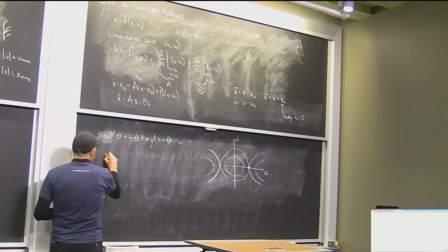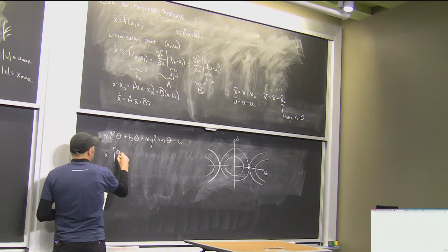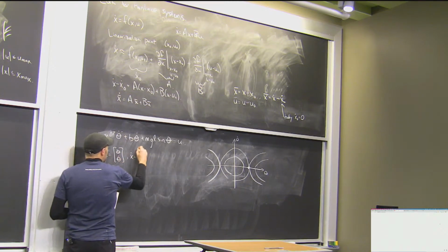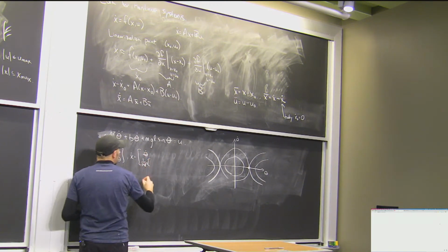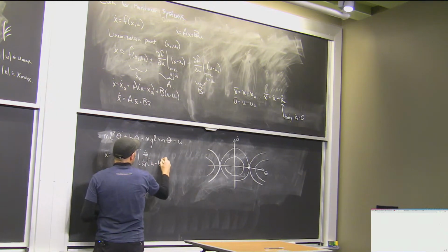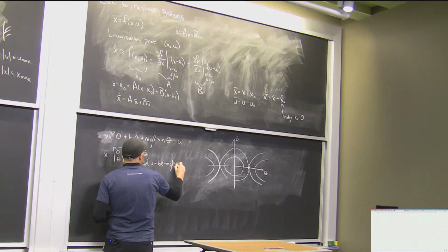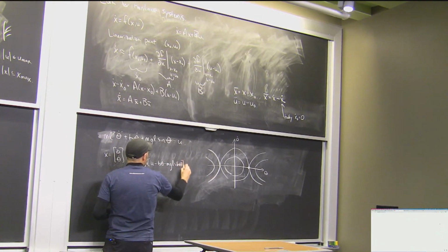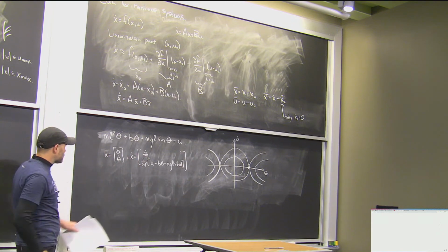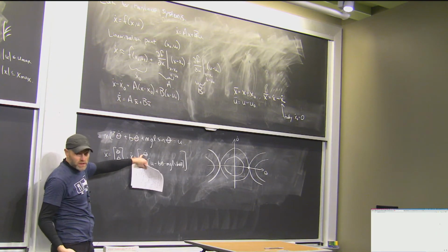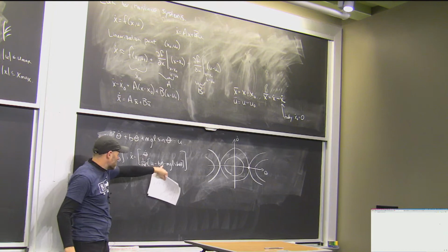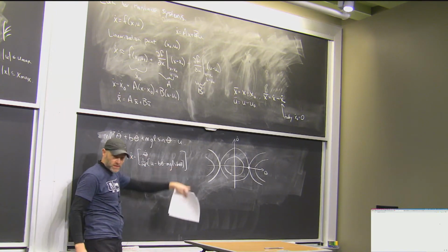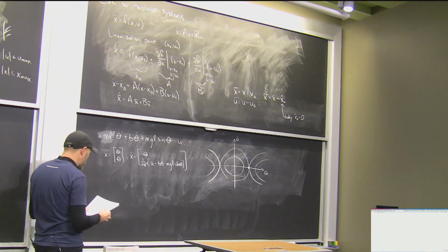So if I were to write this as x dot, I'll write it out just to be careful here: theta dot, and then x dot is theta dot, 1 over ml squared times u minus b theta dot minus mgl sine theta. So this first line is already linear, so my linearization, I hope, will get the same thing back. This one's actually pretty close, but it's got that sine theta that has to get linearized. Okay?